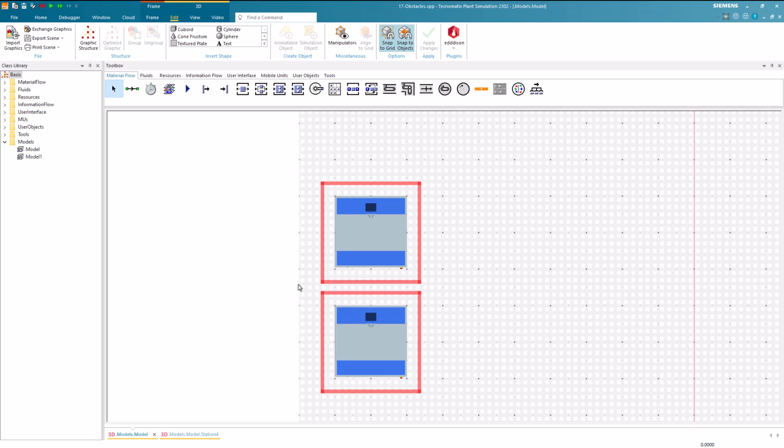This makes in total 0.8 meter, which is usually a shoulder width. So a worker will get through this place, as long as you leave a little space between the bounding boxes of the stations. Or in other words, as long as the bounding boxes of the stations do not overlap, a worker will get through them.